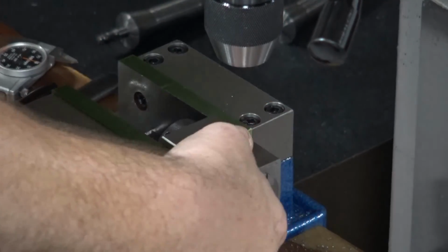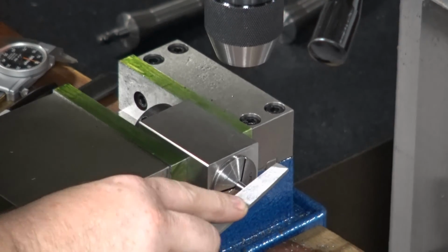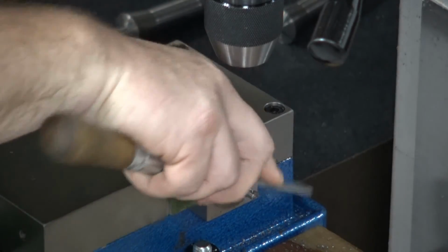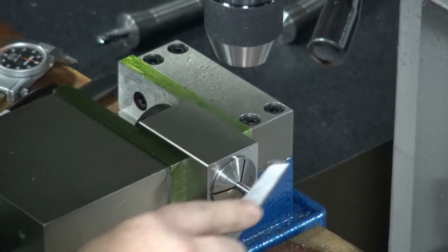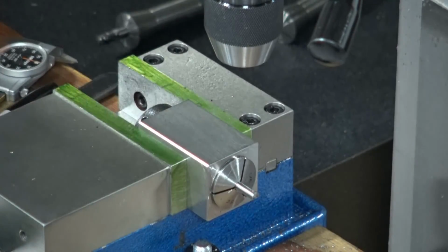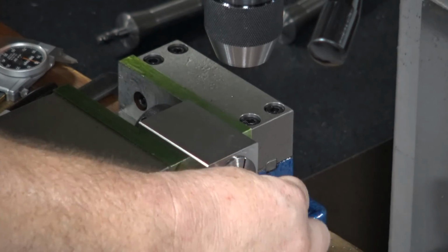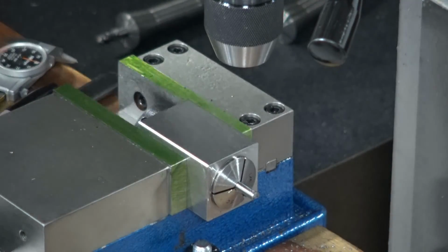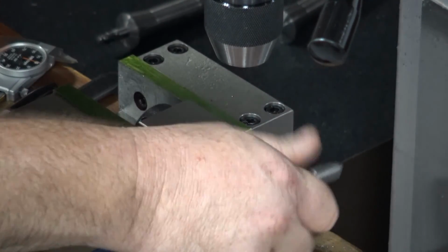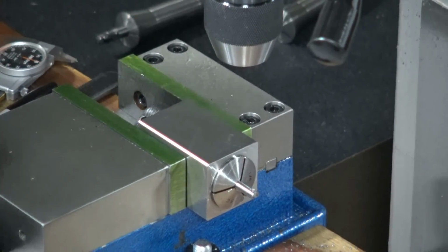While it's still in the collet block, I'm going to flip it over. I'll take my file, and I'm just going to deburr that back side. Deburring the back side is going to get those sharp edges off. And because we're doing a cutting operation, we could have easily pushed a burr over, so I'm going to push that pin right back up through the hole. Clean that little edge with my single flute countersink, because it's going to clean up that edge nicer for me. Once you can run your finger across it and not get into a sharp edge, feel really good about it.